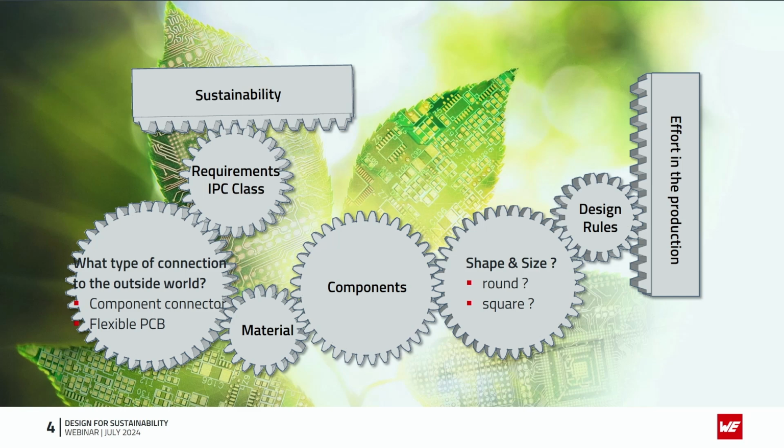Also, when you think about the connection of your board to the outside world, do you have a component connector? Do you have to solder it in? Can it be replaced by a flexible PCB where you don't need the cables in between? Can you use an edge connector? Typically they are made with galvanic gold. Can that be replaced by a printed polymer surface without a galvanic process?